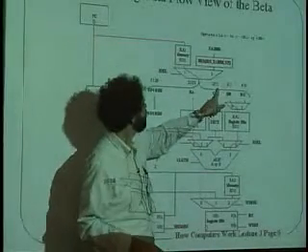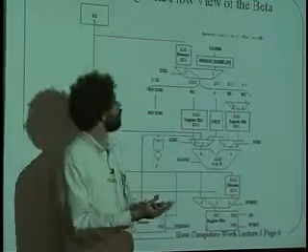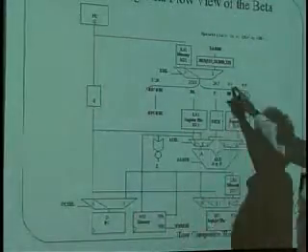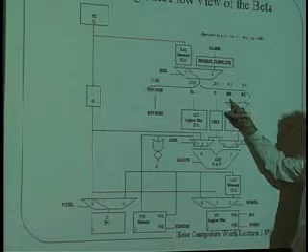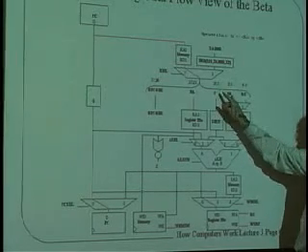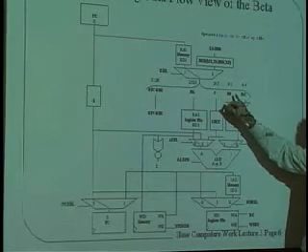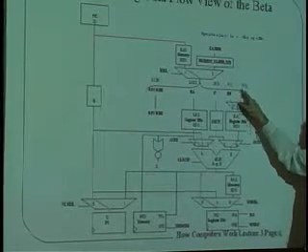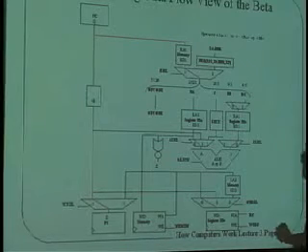It takes bits 5 through 20 and calls that C, the constant. And that's going to be true for those instructions which have a constant as the second argument. It also takes bits 5 through 9 and calls them register B. Now notice there's an overlap between the register B and C here, and only one of these will be used depending on whether the instruction is the type that has a constant in the middle field or a register number. And then finally, the last 5 bits, bits 0 through 4, are broken off of this 32-bit word, and those are register C.